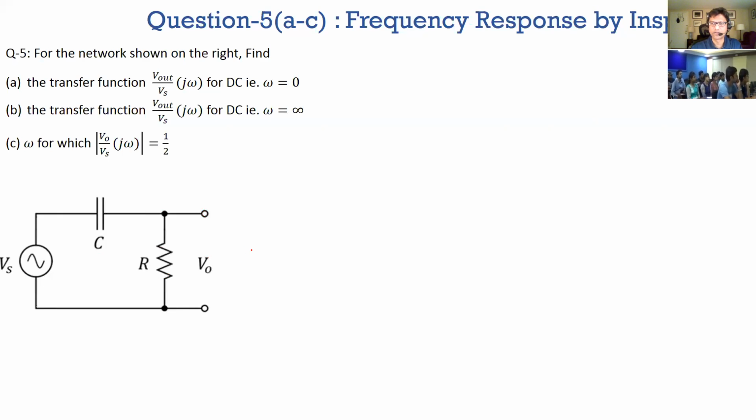Because the impedance is 1 over C omega, so it's a short. What is the frequency response at zero frequency, which is DC? And so that gives you the two asymptotes. And because this is a single pole circuit, you can join those two asymptotes and find the 3 dB point. And I'll show you how to do that. So that was really the purpose. And I could change this to an ARC, and you should use the same principle to find that out.